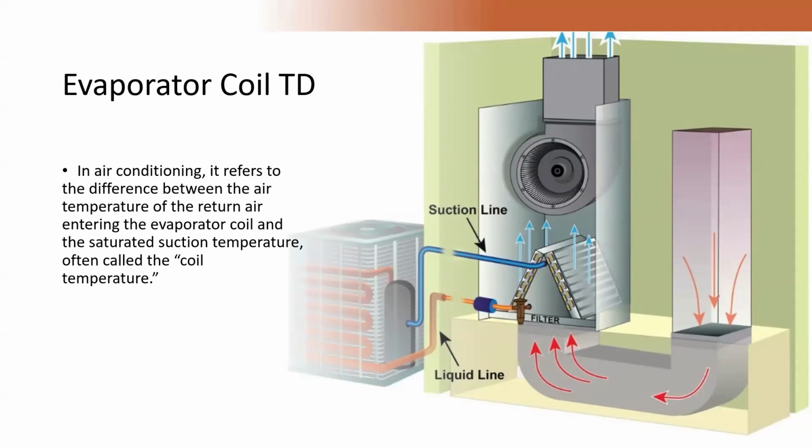Some terminology for those unfamiliar. Several things can impact that temperature differential, including the refrigerant mass flow rate. It's a fancy way of saying how much refrigerant the compressor is moving. Remember, the compressor is a pump, right? How much the refrigerant compressor is moving, how the metering device is performing, the return air dew point, the moisture content, your latent load, and most commonly and most important, airflow.